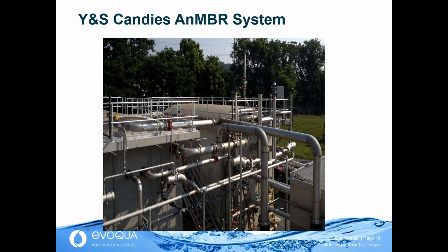So the anaerobic MBR here was designed where we retrofitted an existing hybrid system. The media was removed from the hybrid reactor, and mixers were installed to convert the hybrid into a CSTR. And then we used the CSTR coupled with an anaerobic MBR tank, pictured in the slide here, and that became the anaerobic MBR. So the effluent off the system, and this is the picture that I showed earlier, the influent, mixed liquor and effluent: BOD less than 30, 5 milligrams per liter TSS.